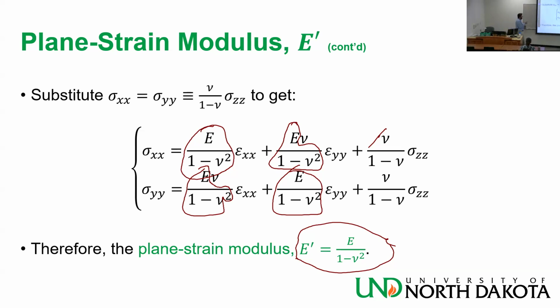So there will always be an error in your simulations with what the equations are giving you. You want to make your model big, big, big. You want to make this hemisphere huge, let's say, but it will never be so huge that epsilon xx and epsilon yy are equal to 0. You need to make it big enough.